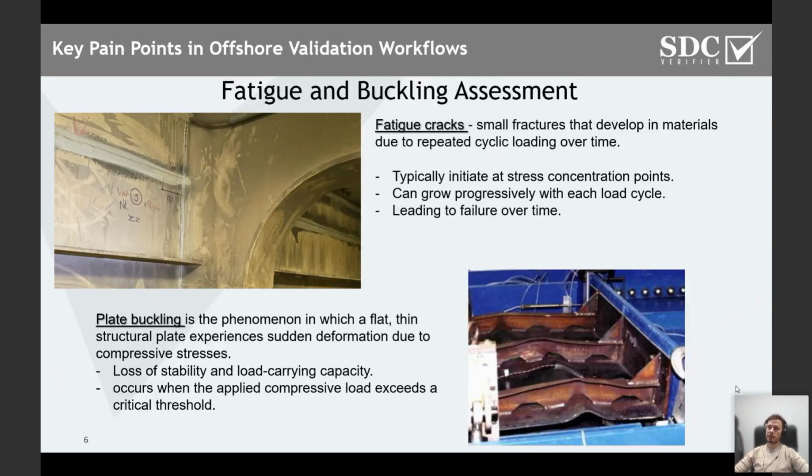So whether it's repetitive working conditions, or some load like wave load, which is repetitive over a certain amount of time, the stress difference occurring in the structure can cause the fracture, the damage, usually starting on some connections like welding, where our notch classes are lower.